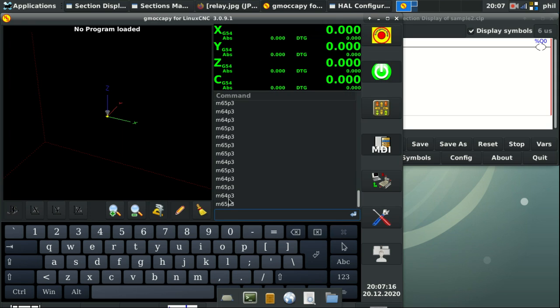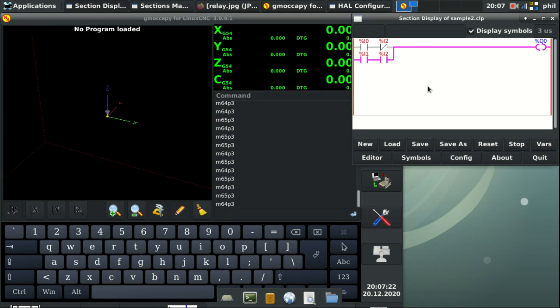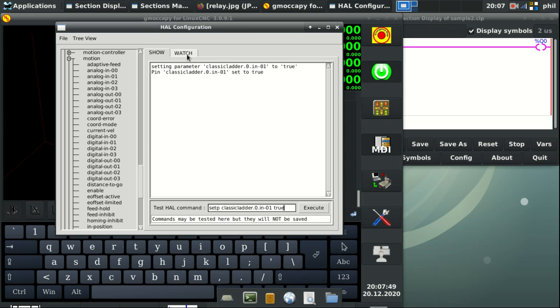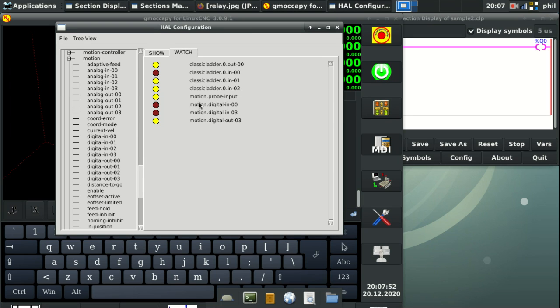So what I want to do is trigger the output, and we'll already see it's making the circuit because we're using the outputs to trigger the virtual relay to complete the circuit. So again, the difference between software simulation and the physical hardware is going to be in our I0 and our I1. In this example, I'm just going to tie those to the digital inputs 0 and digital input 1.